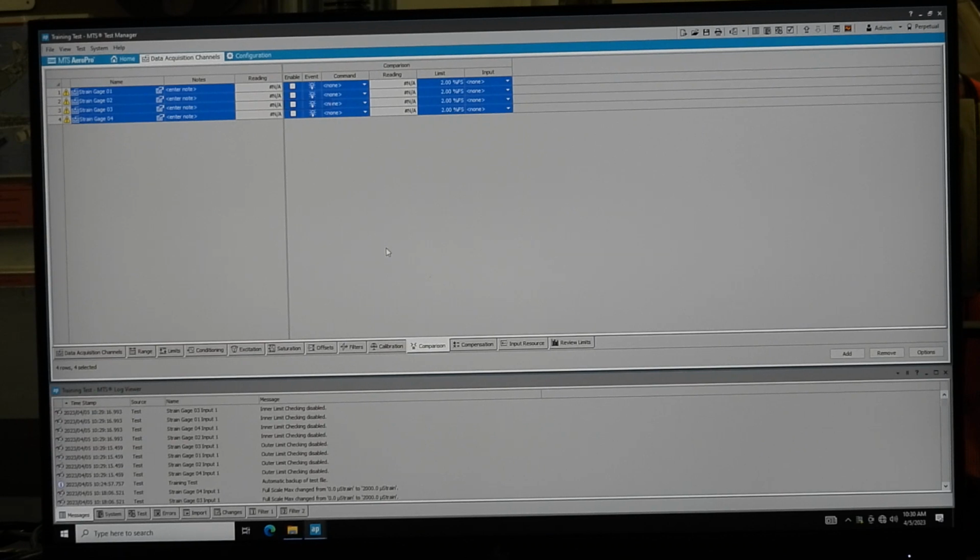So you have two feedbacks from two separate gauge pairs, because if one starts to deviate from the other, you don't know which one is right. If you just have one gauge pair out there, you don't have anything to reference it to, so you don't know if it is actually true.